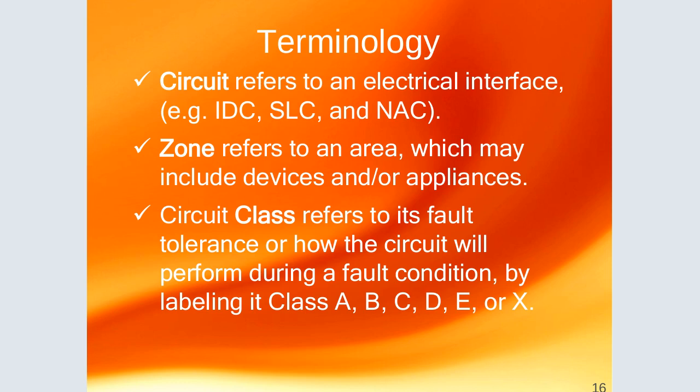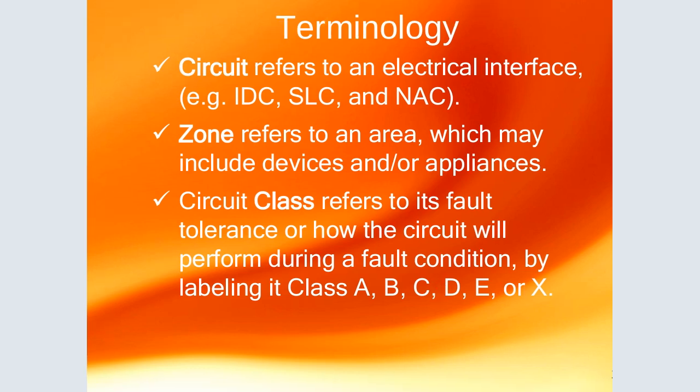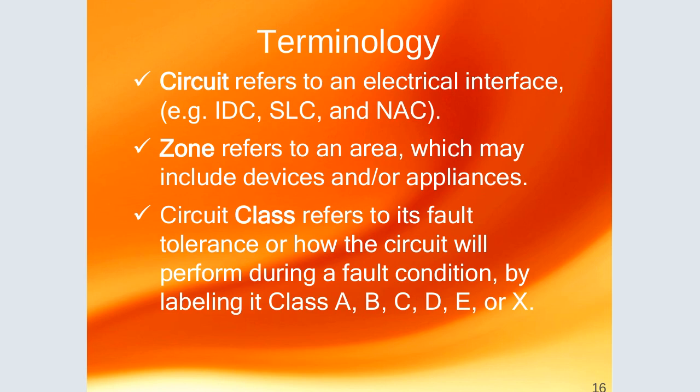Terms like a circuit refers to an electrical interface, e.g. the IDC, the CLC, the SLC, and the NAC. We look at all these circuits. And we'll be having zones. When we are installing the fire alarm system, they are installed in zones. So zones refer to an area which may include devices and or appliances.